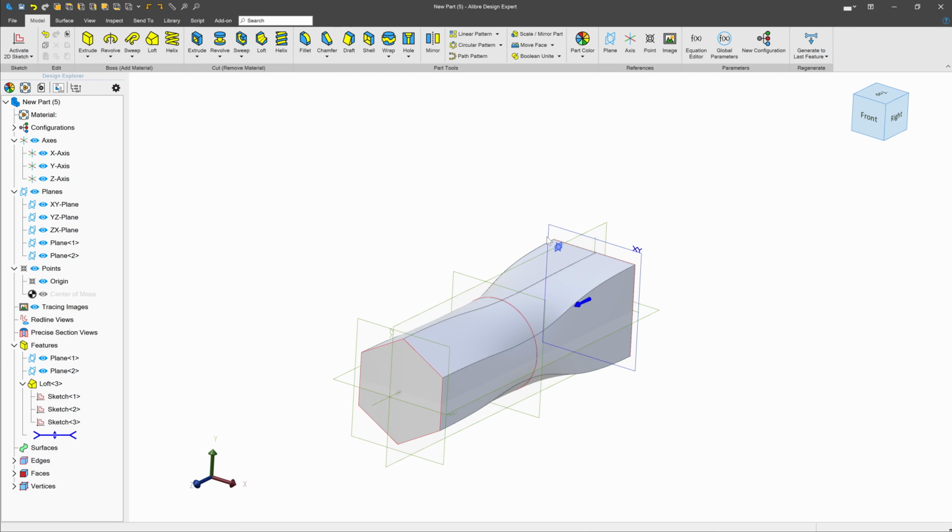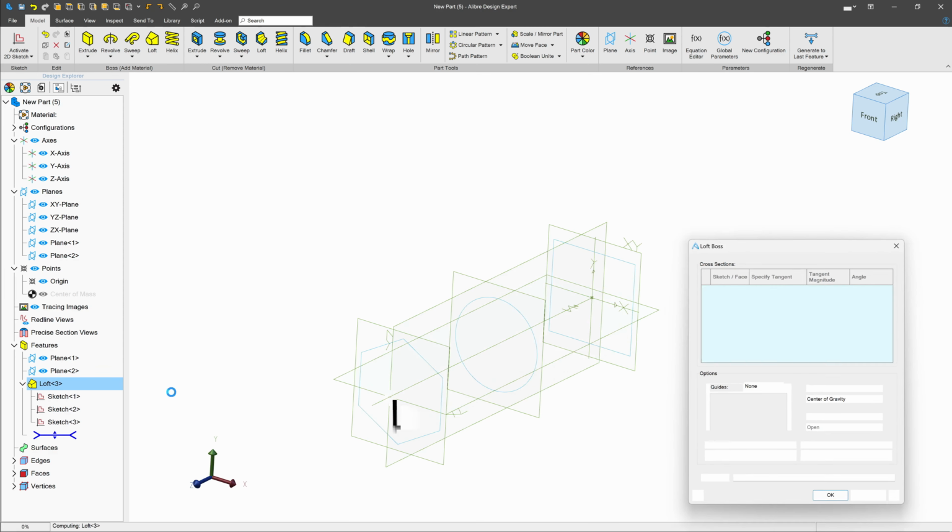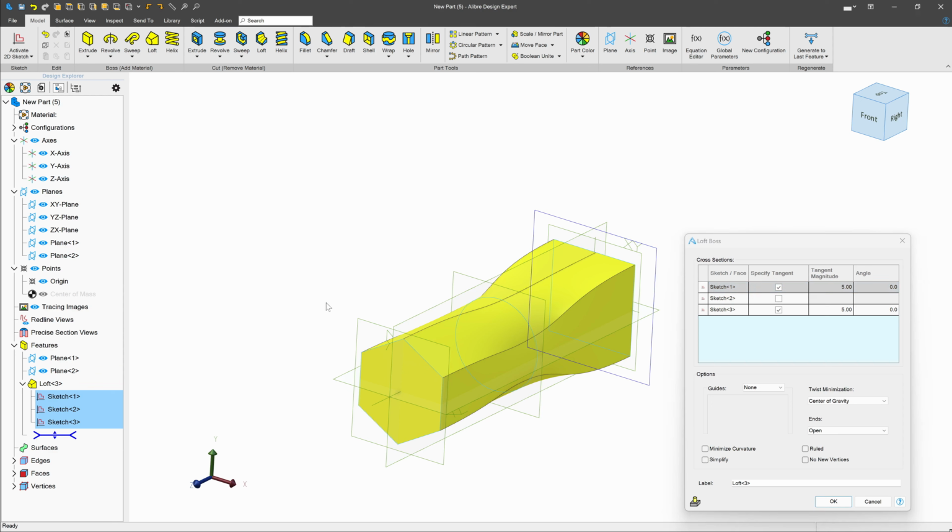Keep the number of elements between your loft the same. And when you do that and follow all of your profiles, you will be just fine, almost all the time. So keep that in mind in your back pocket. If you have lofting trouble, just make sure that you can keep your number of elements consistent. And that is really a lot of the fundamentals of lofting.